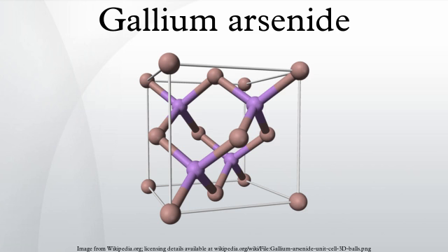Because GaAs and AlAs have almost the same lattice constant, the layers have very little induced strain, which allows them to be grown almost arbitrarily thick. This allows for extremely high-performance high-electron-mobility HEMT transistors and other quantum well devices.